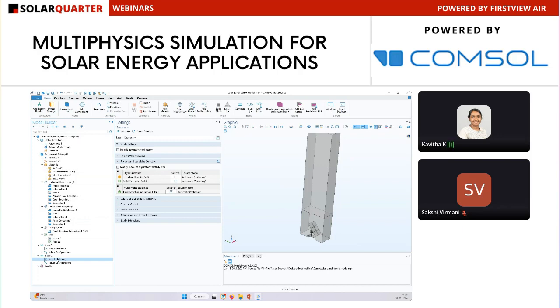Then you perform the study for the solid mechanics to solve for the stress and displacement due to the wind load that was computed using the turbulent flow physics interface. So you can also specify the values of variables not solved for, that you want to choose from the previous solution that you have computed using the stationary study that you have done in the turbulent flow model.